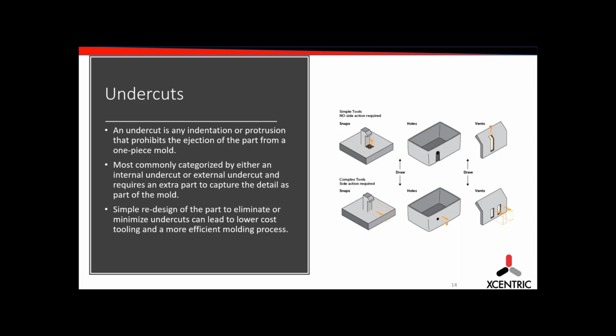Yeah, and it's also going to come down to what the wall thickness of your part is, and how big your part is too. So if you have a really big part and your gate, so a big part with a tiny runner system, yes, your injection pressure. Obviously, there's standard sizes that we would use to mitigate that, but that's going to be more on the mold design side to get the plastic to your geometry.